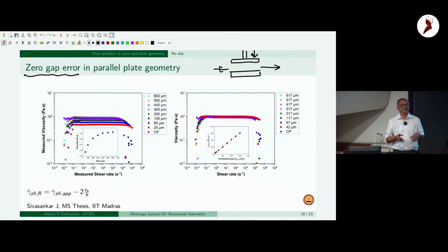It's an estimate in the end, so there can be an error of about 10 to 15 microns in the way the 0 gap is set. The instrument thinks the 0 gap is at some level, but it can easily be 10-15 microns different from that.